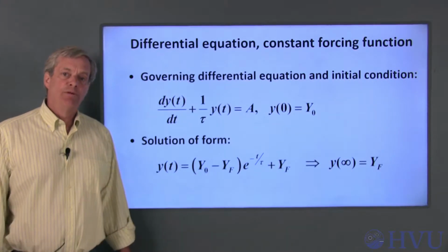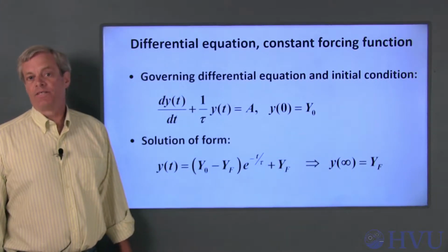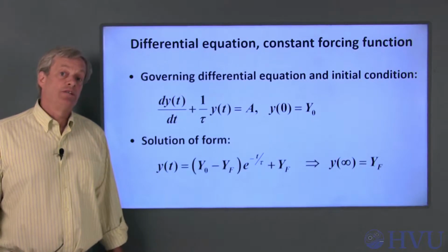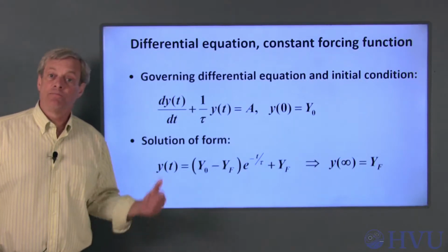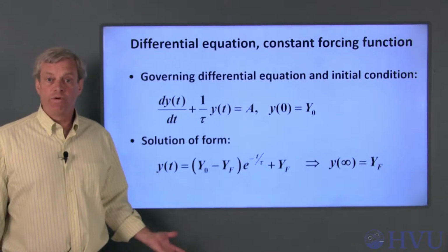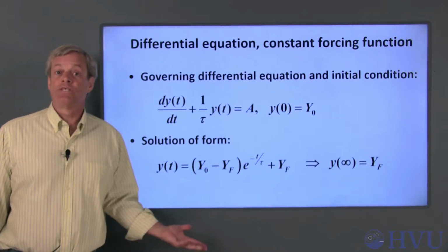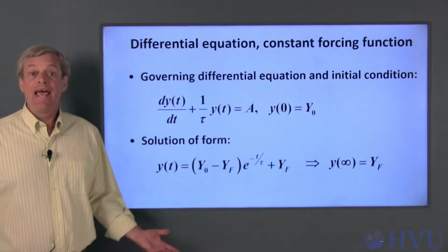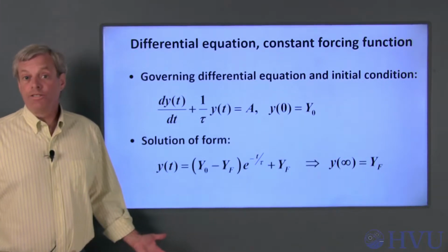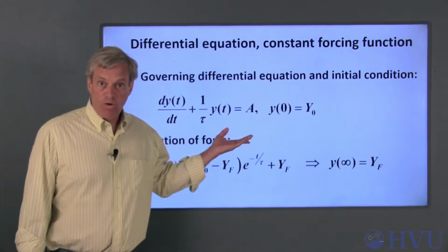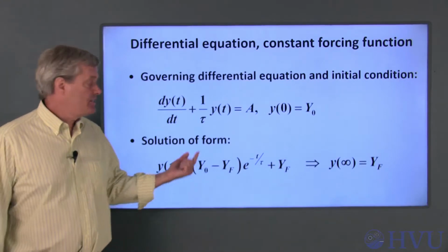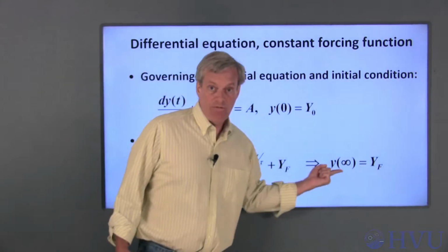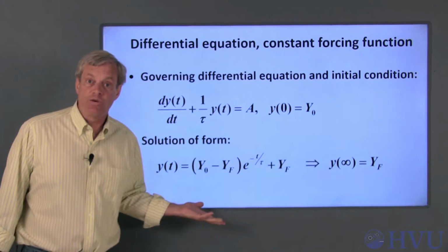This means that we have some ability to double check our analysis of first-order circuits. We can determine the circuit response as we did in the previous video by solving 3 different independent problems to obtain the time constant, the response as time goes to infinity, and the initial condition. Alternately, we can write the differential equation governing the circuit and determine the time constant and the steady state response directly from the differential equation.